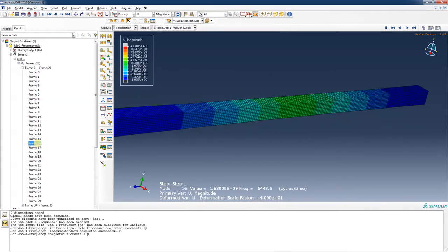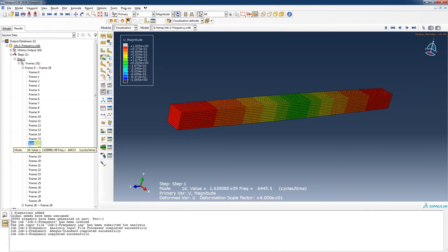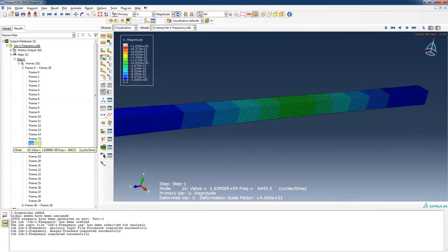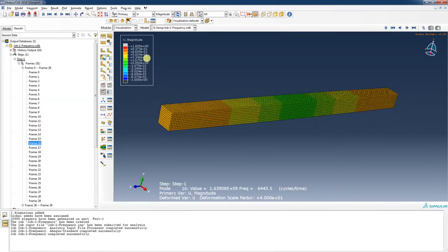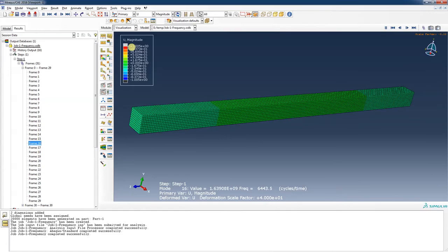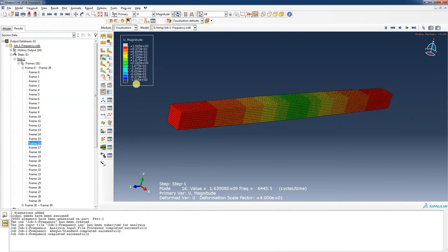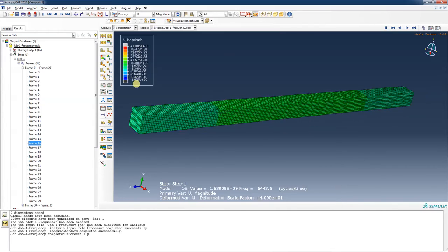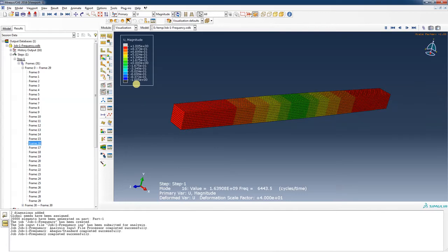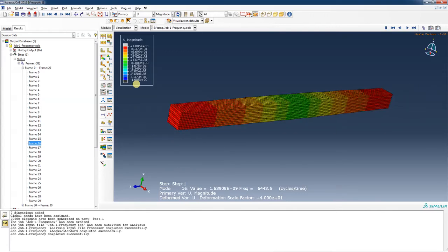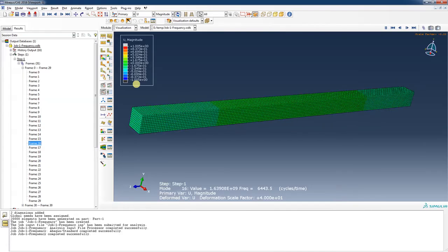So here's an expansion mode. This would not be a beam bending mode that the analytical solution would be able to calculate. And I want to point out the magnitudes of the displacement are all normalized to a unit magnitude. Because it is a free vibration problem, the magnitudes are not defined. They're the eigenvectors, but they've been made into a unit eigenvector, a unit maximum displacement.